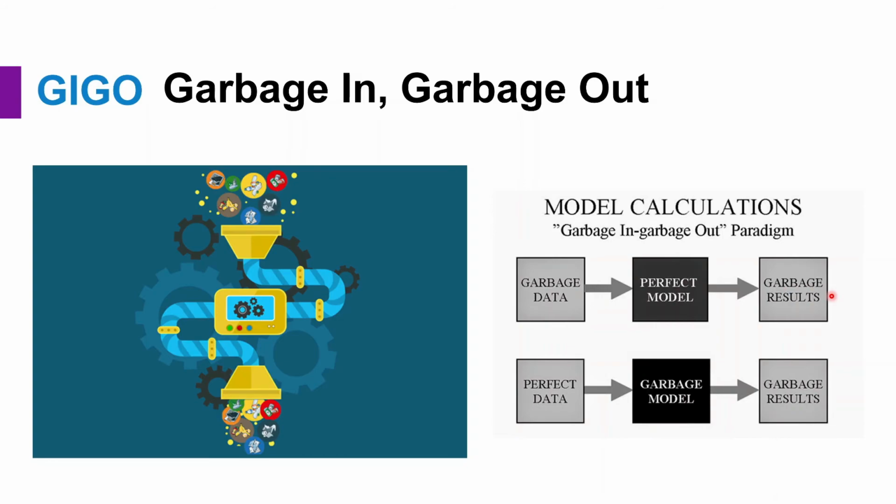Let's say for FEA, you have a perfect geometry, everything designed perfectly. However, the forces I put in are either the wrong amount or in the wrong location, or I haven't considered all the forces. The result I get is not accurate. I can, for instance, say this product is safe to go to the market, but it won't be safe.